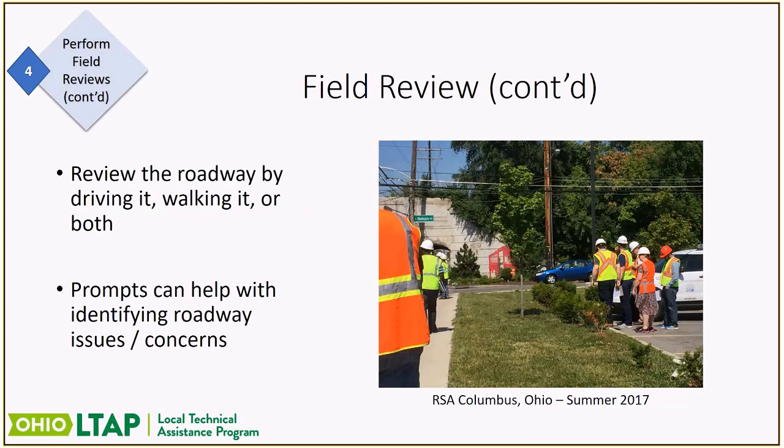So when you're out on the road, and this is a photo you'll see there on the right hand side from a different RSA we did actually in the city of Columbus during the summer of 2017, you want to review your roadway by driving it, walking it. You can do both. There's lists of prompts that you can use while you're out on the roadway. So you can use these to kind of trigger questions in your mind as you're looking, and for your team as well, about what they're seeing out there on the roadway. And I'll show you an example here in a minute.